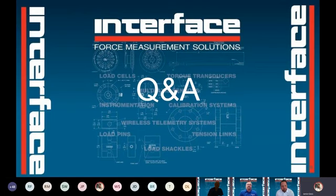Mark wants to know on the plate design, what is the largest amount it can handle in MX? Well, typically these would be based on our 3A series 3-axis sensors. So the largest X or Y load would be basically 4 times the largest capacity minus some safety factor. So maybe divided by 4 again, just to make sure you're well within the working range of the load cells. Ken Bishop could probably answer. I can't remember what the largest capacity is. I think it's 500 kilonewton. So about 100,000 pounds-ish.